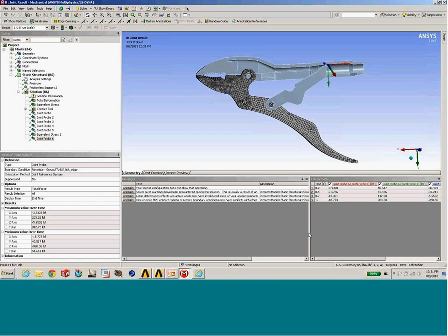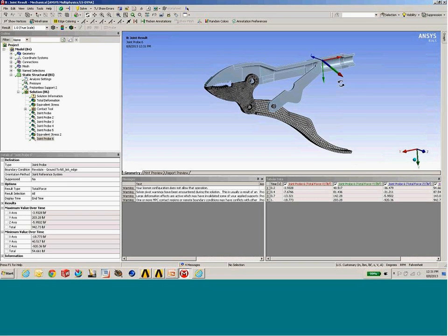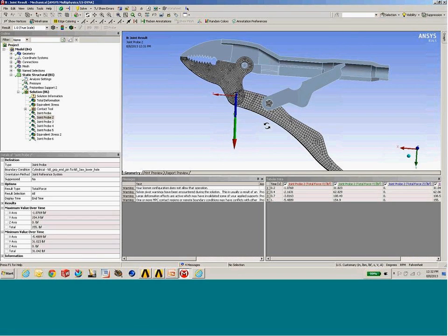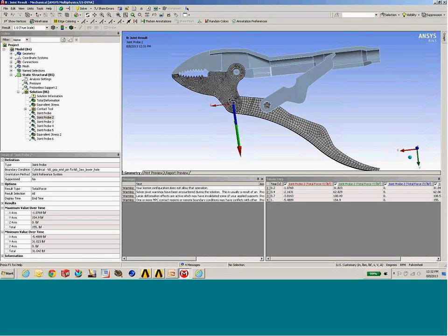and then we simply evaluate the result to get the force distribution. And you can see that's also going to be done on, in this case, a nonlinear analysis with multiple load steps. So you'll see all of the results over the solution history. So it's a quick and easy way to check your results. We'll also do things like give you a net vector of the total load, so basically the SRSS of that load, and the associated vector is shown here.